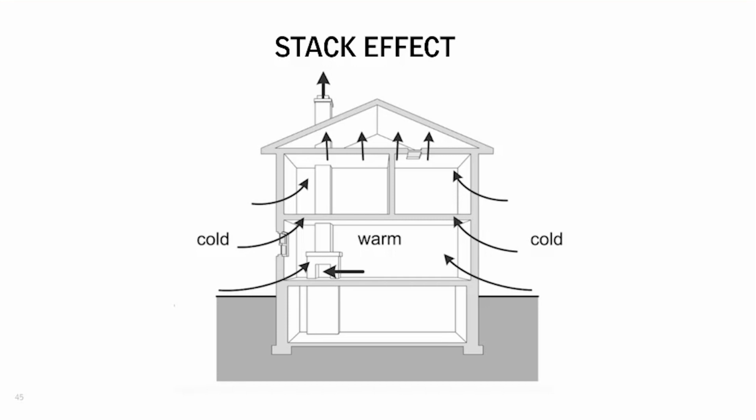Okay, so moving on, the stack effect. Let me define this for you. The stack effect is simply hot air rising. Think hot air balloon. Within a building, when it's cold outside and warm in the building, the warm air wants to push up towards the top of the building. And if it has any ability to leak out of the building, it will pull colder air in through the lower building. In a very tall building, you'll actually have an equilibrium at the point in the height of the building where the positive pressure at the top transitions to negative pressure at the lower part of the building.